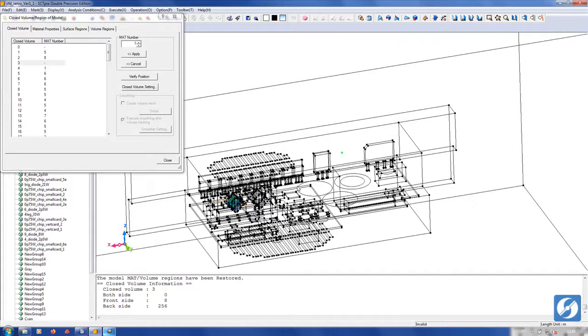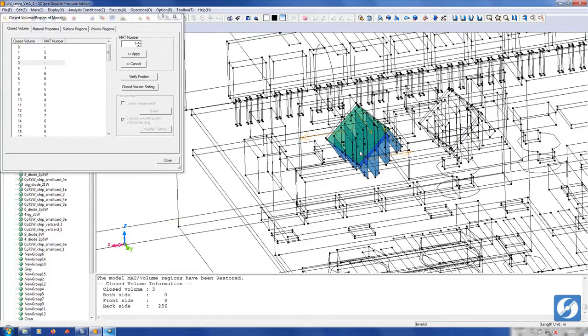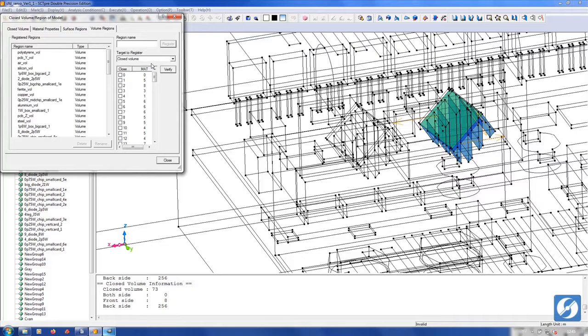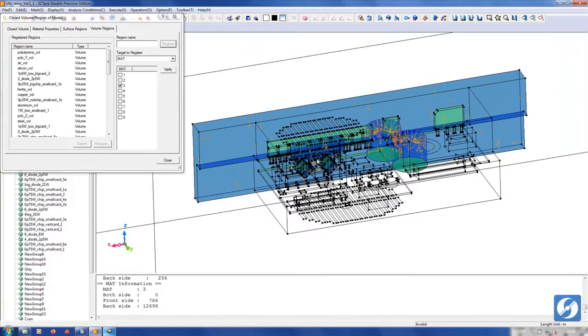The two it could not handle are the newly added heatsinks, which will not have assigned material numbers, so they are easy to find and easy to add aluminum properties to manually. I also add these two to the group that has all aluminum parts in it.